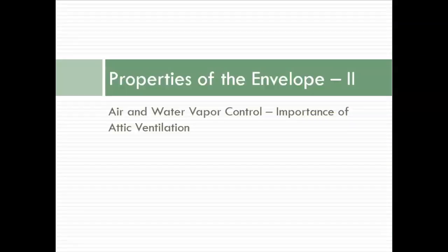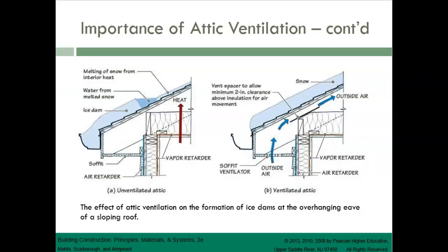Let's take a look at the importance of attic ventilation. Ventilating the attic is necessary for reasons other than condensation control. In cold climates, ventilation prevents the formation of ice dams at projecting roof eaves.